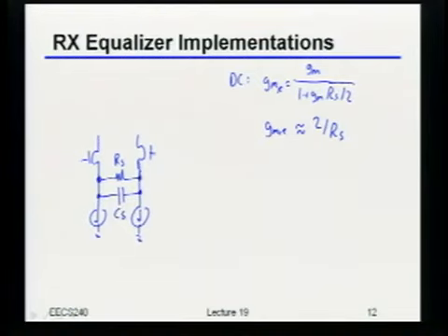Oh, yeah. Sure. Because all that capacitor is doing is, at high frequencies, you want to get the full GM back. In other words, you want to short the two tails together, right? Well, how do you do that? You put a cap in parallel so that at high frequency, the impedance of that cap goes to 0, right? So now, at high frequency, of course, the effective GM will just be equal to the nominal GM, right?